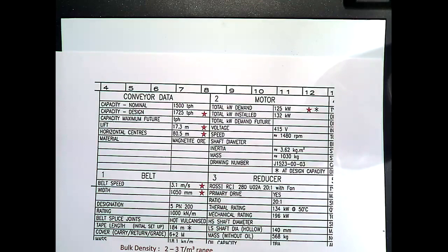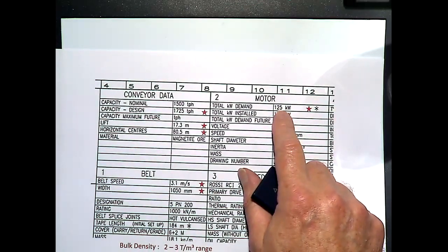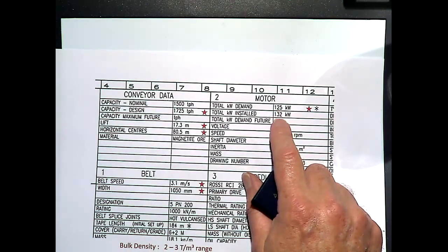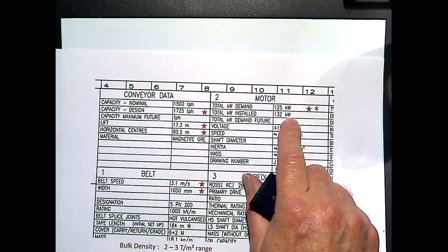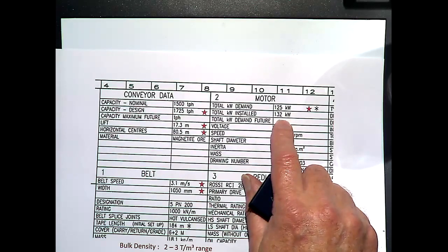Okay? And so what we found here is that we calculated 115 in their drawing. They said that there was 125 kilowatt. They installed a 132 kilowatt motor. Do you know why they didn't install a 125 kilowatt motor? Because mechanical guys aren't electrical engineers, and electrical engineers don't make 125 kilowatt motors. And it's funny because the next one up is 132. And you kind of think, oh, 125 seems a better number to go for, but they decided that the number